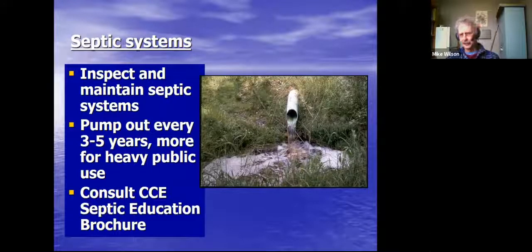If you have a septic system, or some of your park systems, you may have septic systems in your parks for your bath facilities. You want to inspect and maintain those septic systems, and you want to pump them out every 3 to 5 years. More so if there's heavy public use, especially your parks.